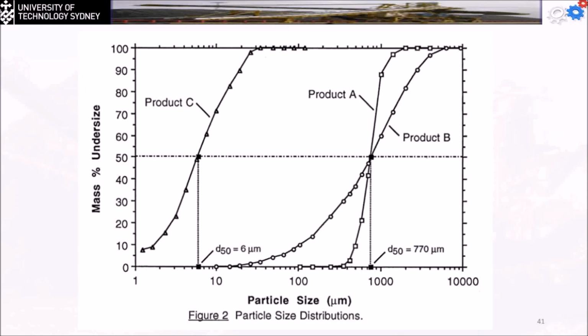Now, one of the tests we can do for the material is the bulk density and the compressibility of the material. What will be the use of the compressibility? How compact you can make it and transfer it. So you can fill the same bin with more material. But this is not always a good thing, and that's what you're going to see next. Some material will break, and they're going to be held inside, so it's going to be harder to take it out.